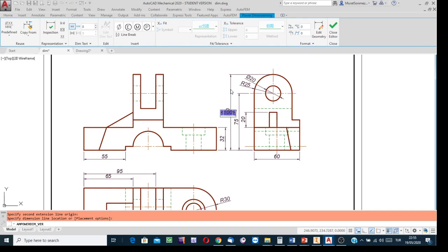But here, since 75 plus 25 makes 100, adding the other indicated dimensions can find the overall height, then in this case, overall height is a reference dimension. And what does it mean? Reference, if it is reference dimension, overall height may be reference dimension, overall width may be reference dimension, overall depth may be reference dimension. In which case, whenever the overall size can be computed by adding the other dimensions which have been shown on the projection, then say that it is reference dimension.